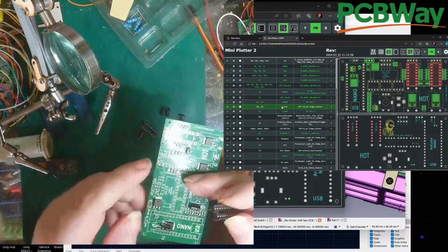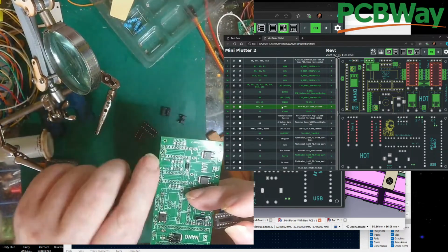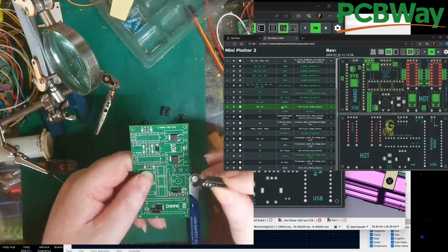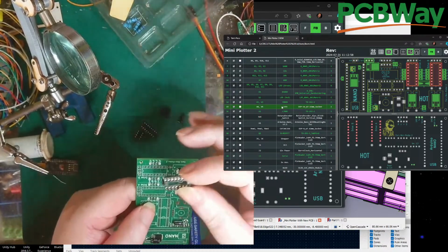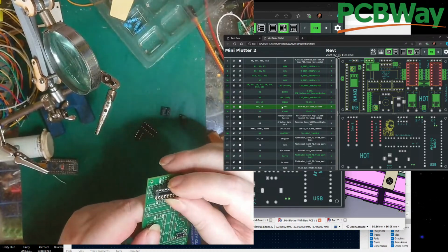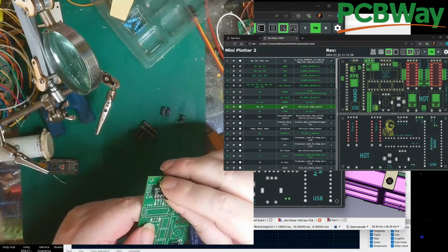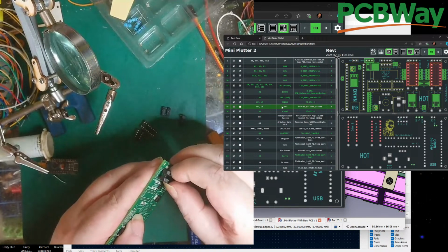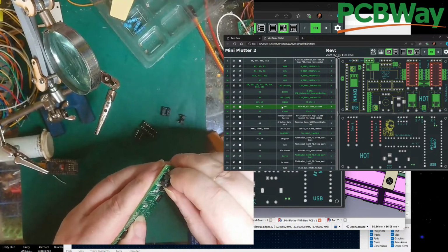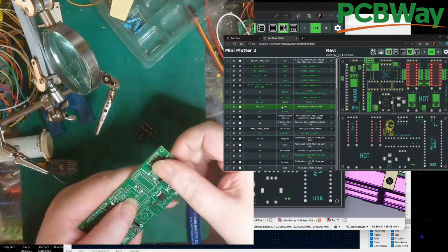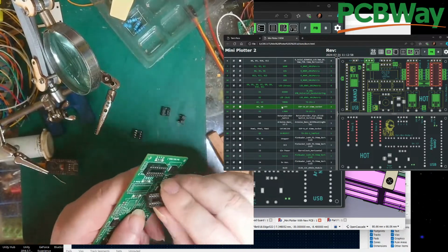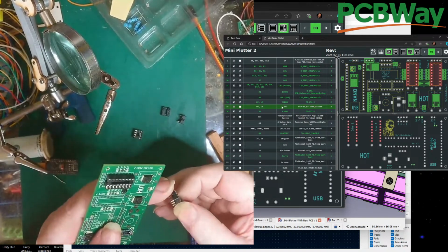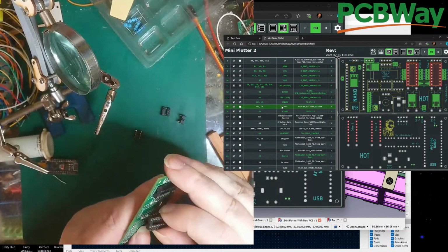We've got a little marker. That's pin 1. It's got a little dip, and then we've got a little dip in the socket as well. So hopefully, when we're sticking the sockets in, we're going to get them the right way around. And that's that one. And then do the same with... Oh, we've got a bent pin there. Can I straighten that?